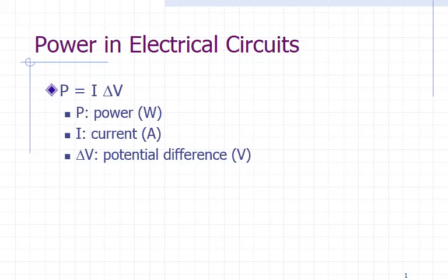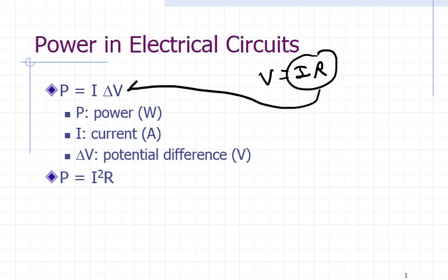All right, so we've already derived the power equation, current times voltage, to get power. And if we use Ohm's law, we can rearrange this to get what we need. So V equals IR. So instead of using voltage, we could place this in for voltage. And then we would have I times IR, which would be I squared R, equal to the power. So if you just have resistance and current, you can figure out the power.